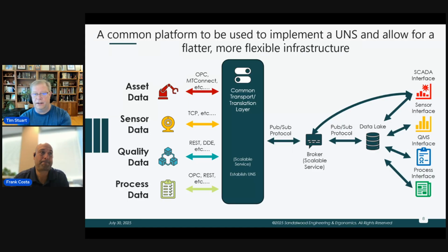Yeah, absolutely. For me, having that broker there helps. It makes sense to me, especially in a brownfield environment where you've got a mix of different sources, and MQTT is one source that's feeding into that, but it's a source that's really easy to set up and configure and connect some of those things that wouldn't otherwise have an OPC connection into that data broker and so forth.